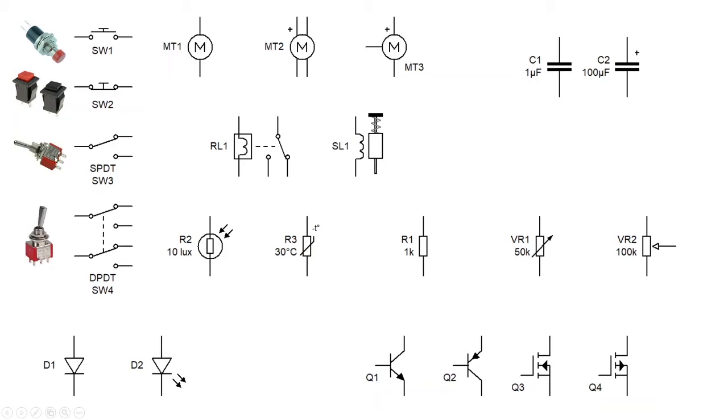This one here, you'll notice it's got on and on written. You can have it on that way or have it on that way, depending on which way the toggle is. Okay, so single pole, it's just one circuit. Dual throw, two options. Here we've got a dual pole, dual throw. Now you'll see there's two rows of spades here. So you've got two totally independent circuits being switched on by a single flick.